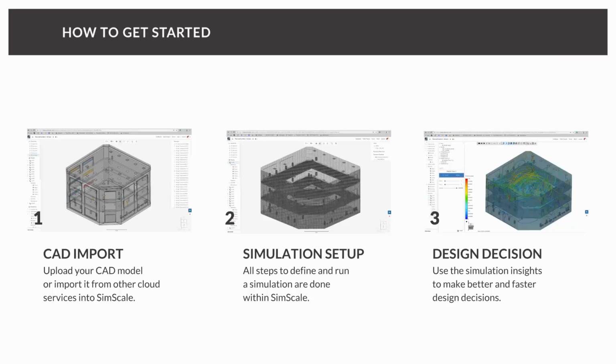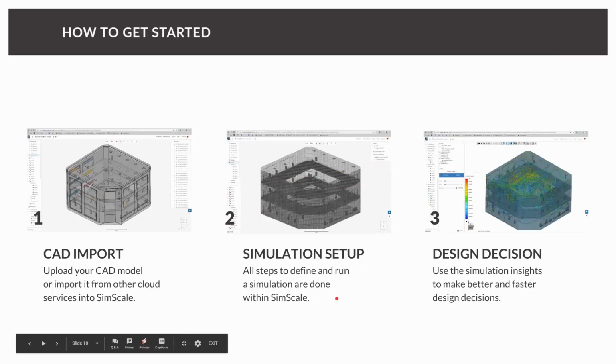And once this is done, you just need to define the boundary conditions, which describe how your model is interacting with the environment. Then you can start the simulation. And finally, when the simulation is finished, you will get notified. In this case, where we have a large simulation, it can take some hours. And then you can download the results if you want, but you can also visualize and analyze them inside our SimScale platform.